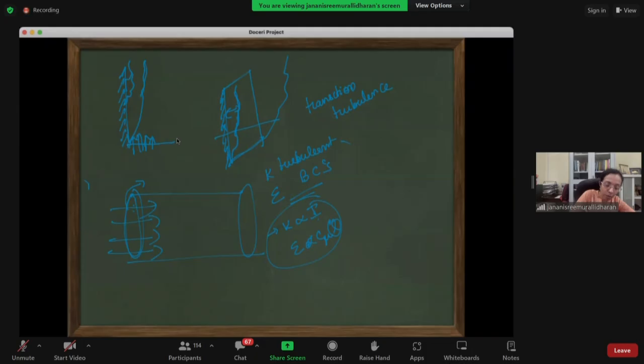So here you will have a place where it will monitor your Reynolds number and see if your velocity is moving into the turbulence regime, and then switch on a turbulence model. So you'll have to start using only transitional turbulence models. I think you have one or two transition turbulence models in OpenFOAM. So you'll have to use that rather than a pure K epsilon equation.